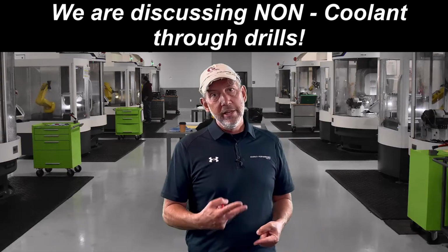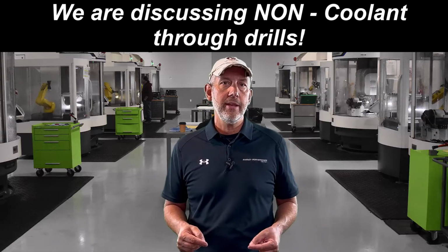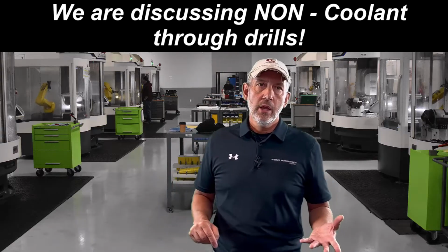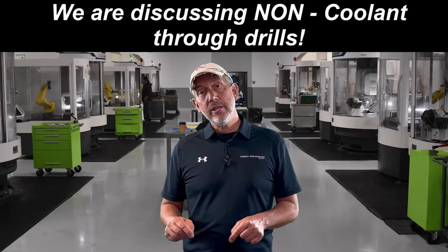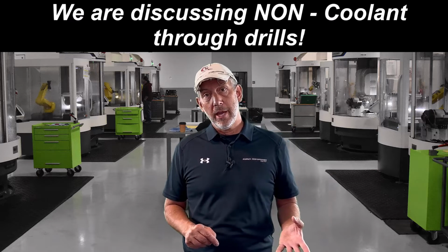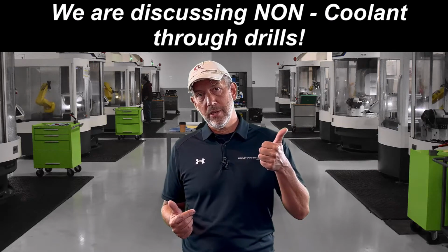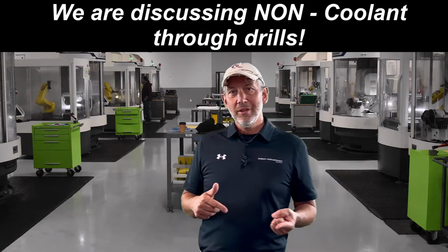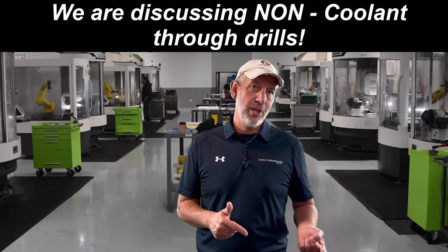That's number one. Number two, you're also going to look at pecking based on the material. Now, why would I say the material? Well, all materials make a chip, right? Remember what I said a drill does? It makes a chip, holds a chip, evacuates the chip. So all materials make different shaped chips.